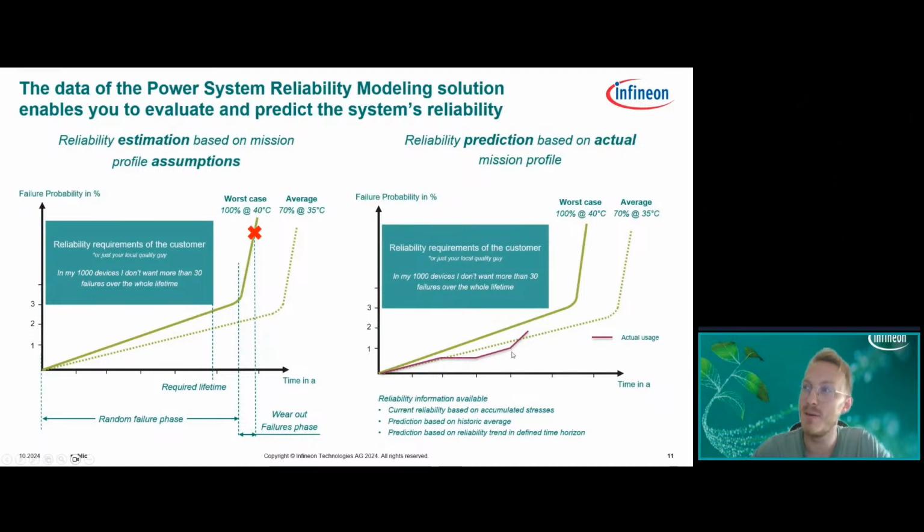And then at this point in time, for some reason, the failure rate got very steep, actually worse or steeper than your worst case assumption, indicating that this device is overstressed. Now you can essentially use this Y parameter that you have at this point in time as an indicator of how much it was stressed.